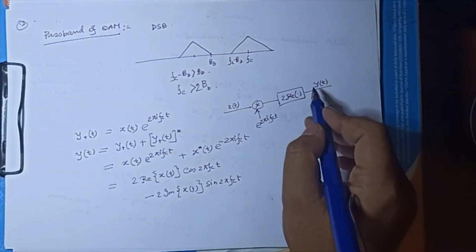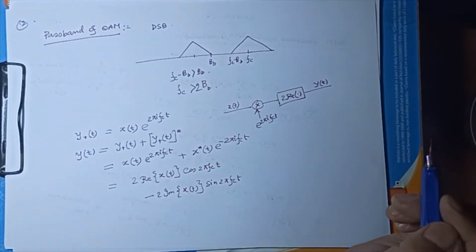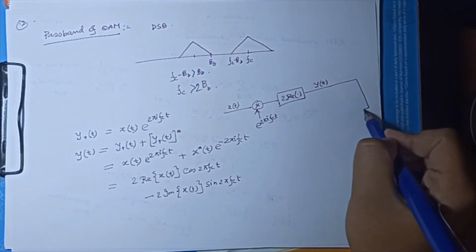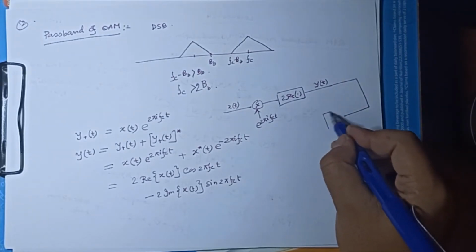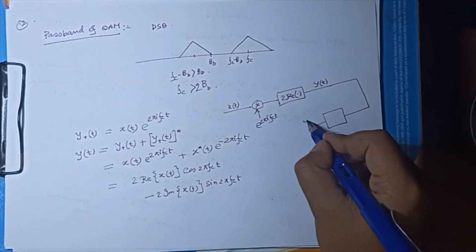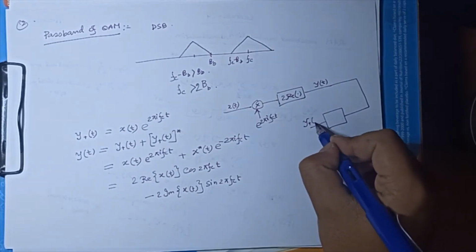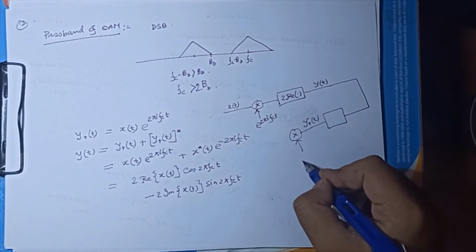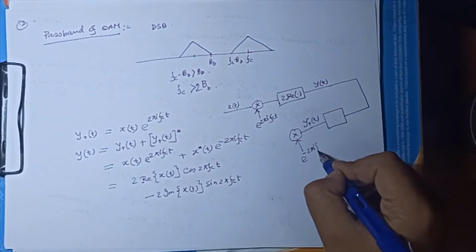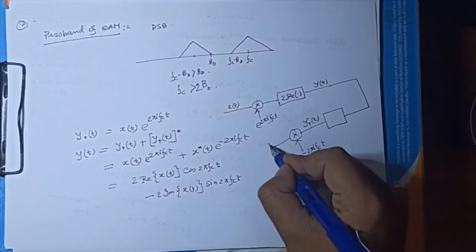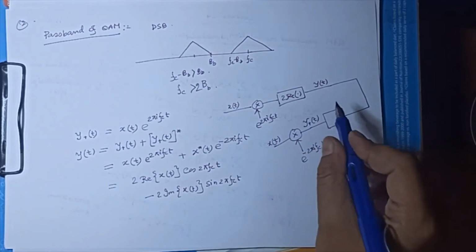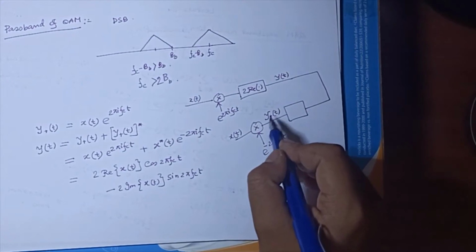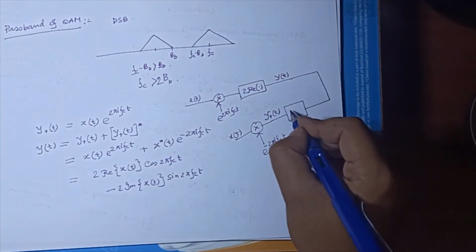Now from y(t), if you want to get back x(t), you first have to transform y(t) to y_+(t). So somehow you have to get y_+(t). Once you have y_+(t), the next step is simply modulating back by e^{-j2πf_c t}, and you will get x(t) back. So what can give you the analytic waveform x_+(t) from y(t)? This you have seen already.